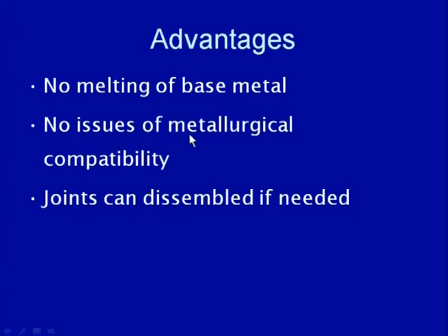This can adversely affect the corrosion performance. Otherwise, as far as the bonding is concerned, the metallurgical compatibility between the filler material and base material is not a major issue in the case of braze welding.